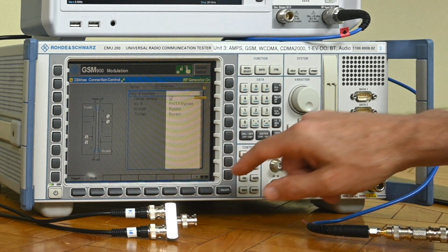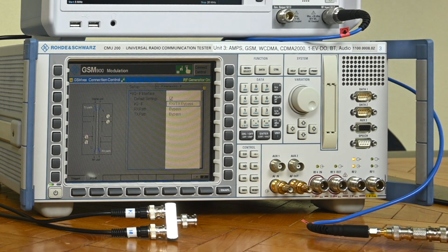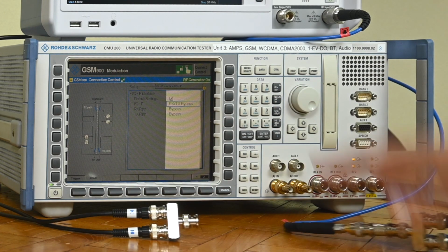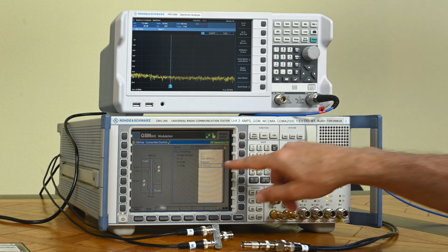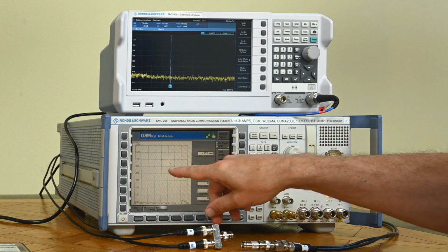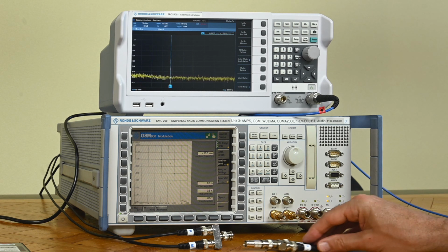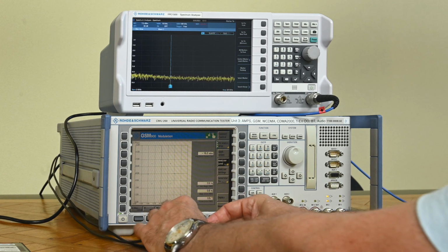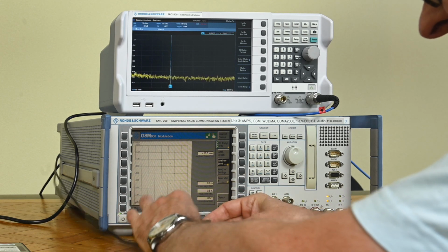We've got a trigger scheme, the IQ scheme. So now I basically want to test whether the insert loops well. So I'm choosing IF in/out for that one. So I got my constellation back. So I'm on the transmit path. If I disconnect this here, it should disappear. Yeah, transmit path. Then it's gone.